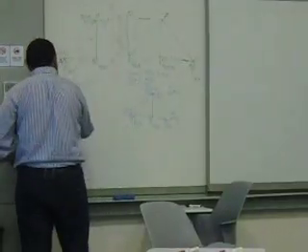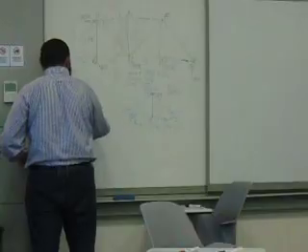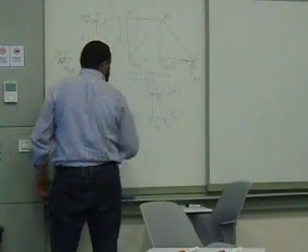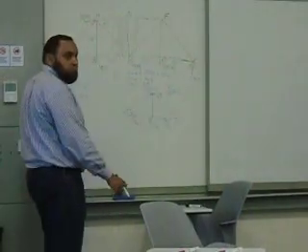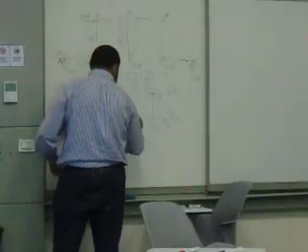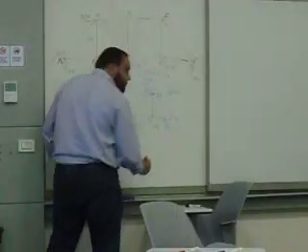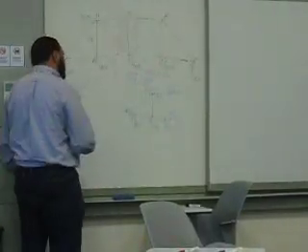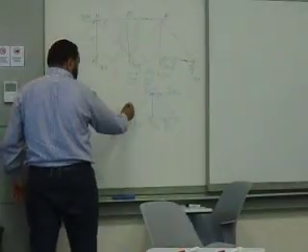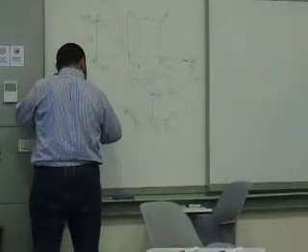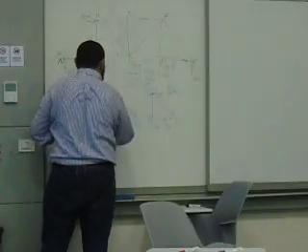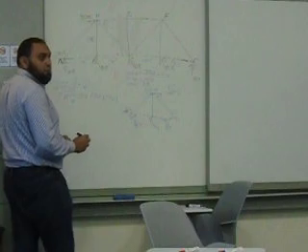So if I simply take sigma moment about H equals 0. Now I'm getting rid of this one, and I'm getting rid of the 30, and I'm even getting rid of the 40. Right? So what will I have? I'll have this 30, this 50, and this FBC. So now I'm assuming that this is the positive direction. So acting in the positive direction is the 30 times the R, which is 20. Following me? Okay.